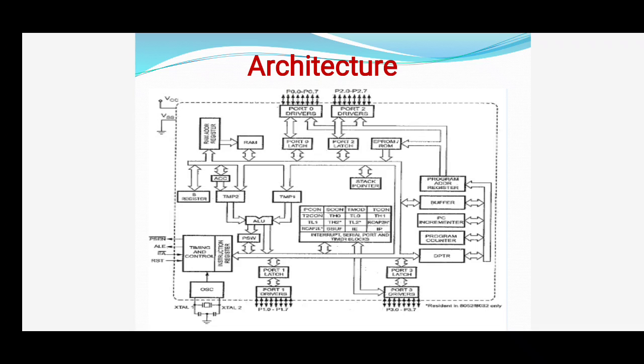Lastly, the block is for interrupt, serial port control and timer control. The microcontroller has 2 timers, 1 serial port and interrupts, which are controlled by this block. SFR stands for special function register. SFRs related to timer, serial port and interrupt control are stored here, which are actually a part of RAM.